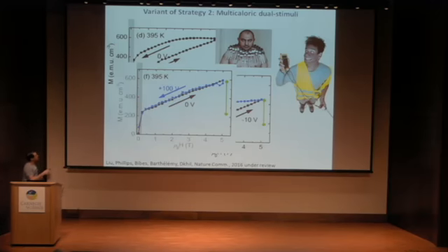You have magnetization as a function of magnetic field, on heating without voltage, on cooling with the voltage. So you use the two stimuli to suppress this hysteresis loop, which is very bad for caloric properties because of losses due to a Joule effect, for instance.